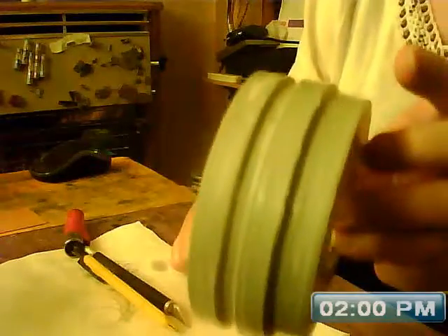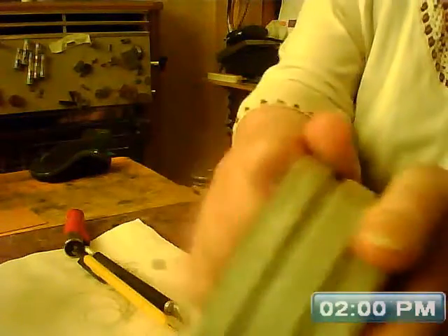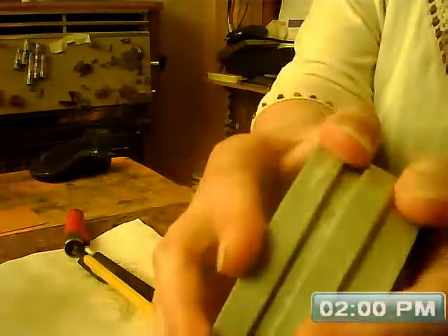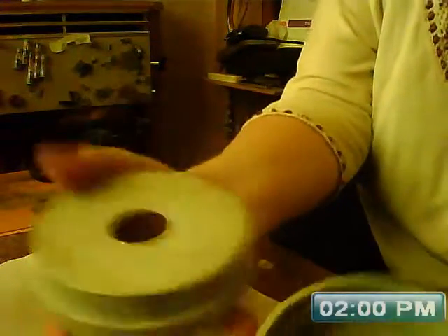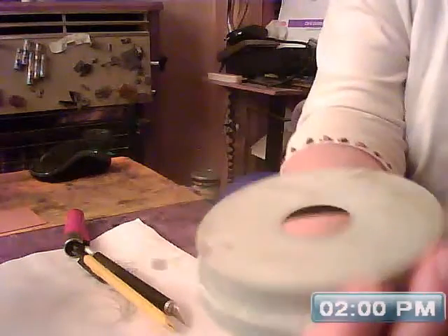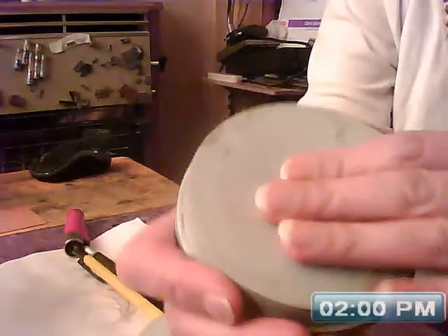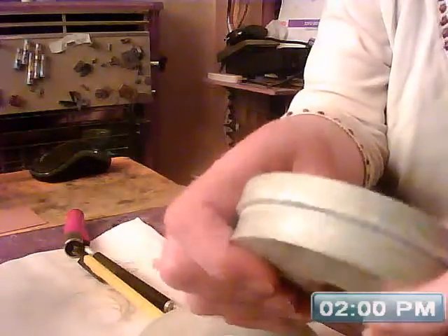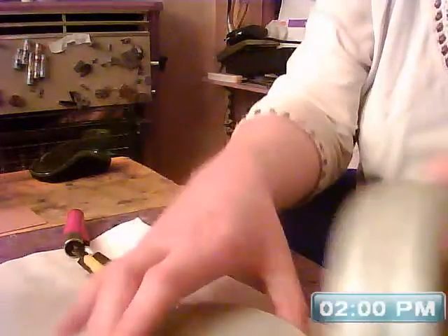2 printed, and they're stuck together. Look at that. Press fit. I had to twist them apart. Perfect fit. So I got my dimensions. There's a slight bit of bowing because of the shrinkage, but this one's come out better. Actually, they're both slightly dimpled, but that's no problem because when there's suction going through there, these tend to pop in anyway. So I need to make sure there's no clearance on there, but they basically just fit.